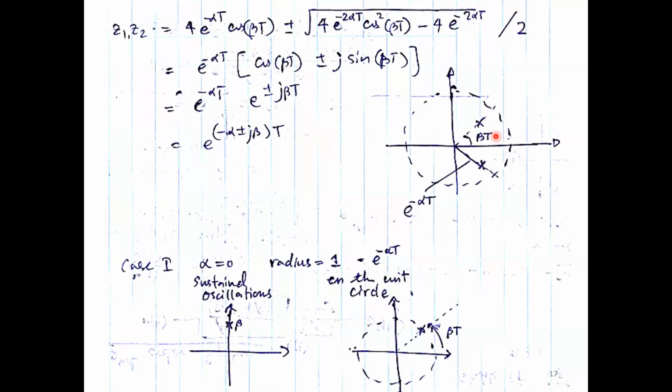And you know that if you want to sample a sinusoidal signal with minimum accuracy, which is not anyway sufficient, this angle has to be less than 180 degrees. You know that, no? So if you are sampling a waveform, let's say a 10 hertz waveform, what is the minimum sampling frequency? Can anybody tell me? There's a sinusoidal waveform, let's say 10 hertz. So every 1 second, it goes through 10 cycles. If you want to discretize or record this waveform as a set of samples, what is the minimum frequency you should apply?